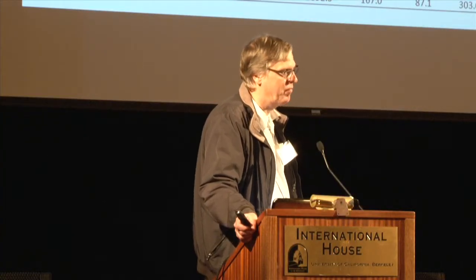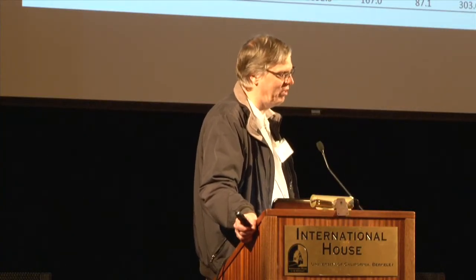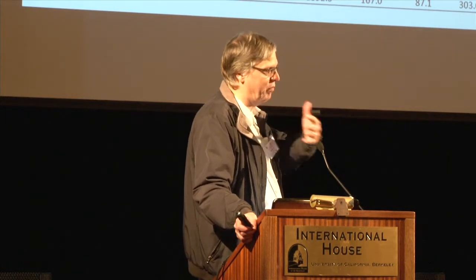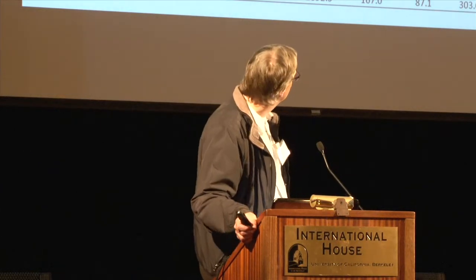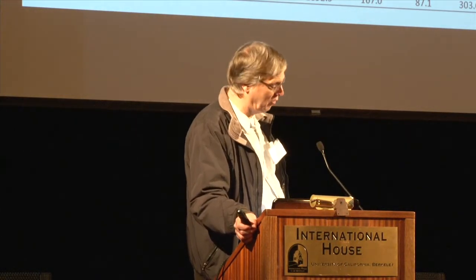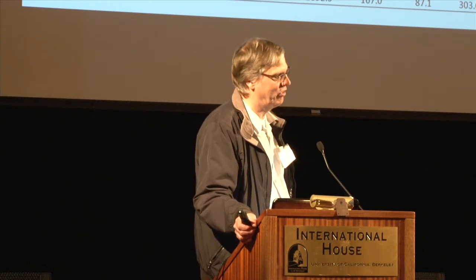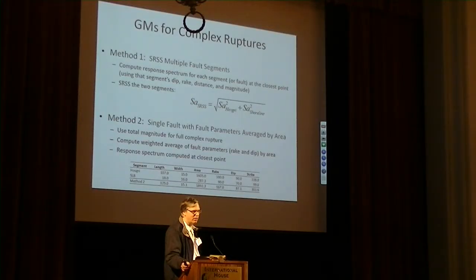Okay. So I think you could say the concepts of RVT may be breaking down at 10 seconds because the periods are so long, but that's not going to be a controlling source for us. So I will defer that to interesting science issue or statistical model, but not really relevant to our hazard calculation. At 10 seconds, it's consistent with the simulations for the SRSS. So if the simulations are working right, which are just summing in the time domain, then the SRSS is still working at 10 seconds. So it's the magic of SRSS.